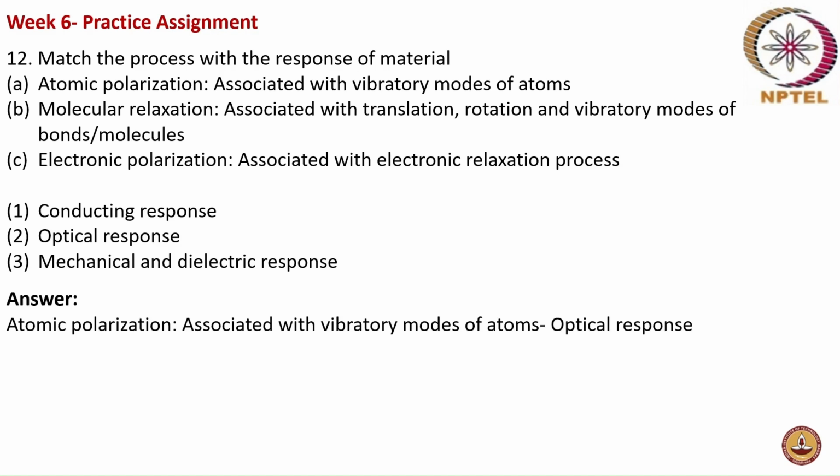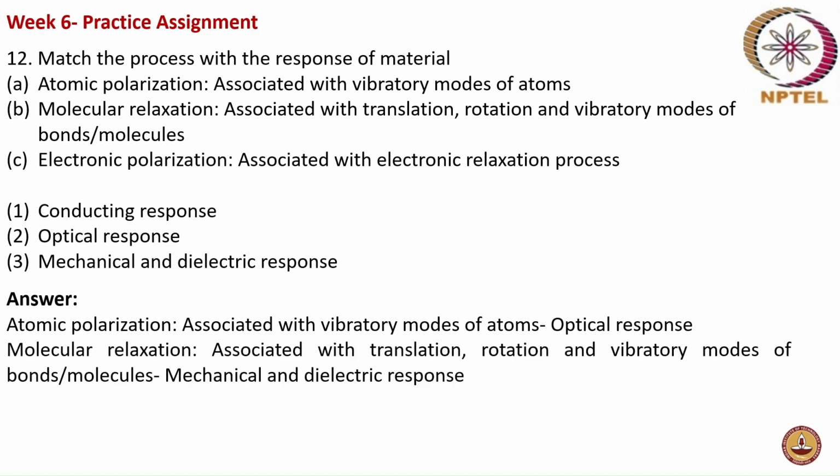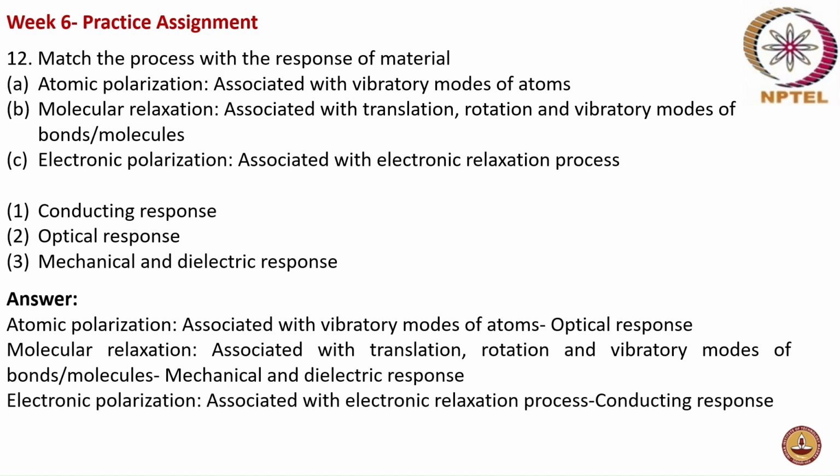It is actually atomic polarization, which is associated with vibratory modes of atom. It gives you the optical response. Molecular relaxation process, a molecular scale process that is happening only, gives mechanical and dielectric response, which is associated with translation, rotation, and vibratory modes of bonds or molecules. And finally, electronic polarization is associated with electronic relaxation. It gives the conducting response.